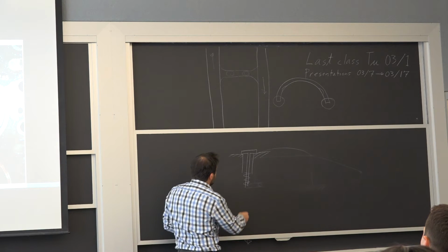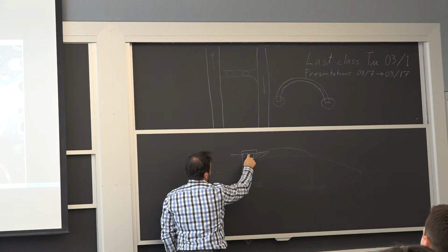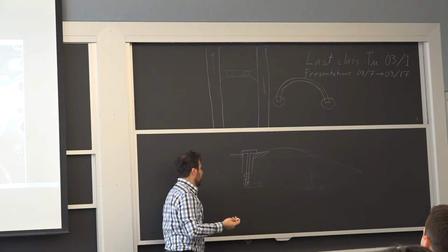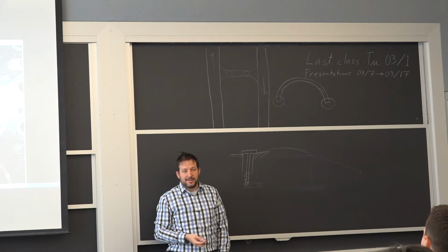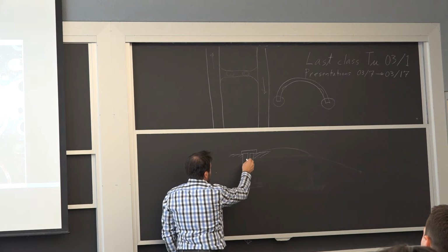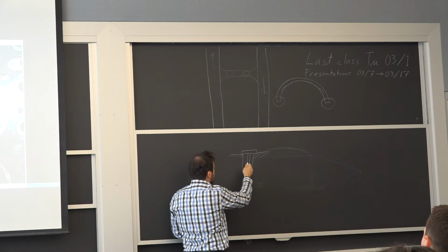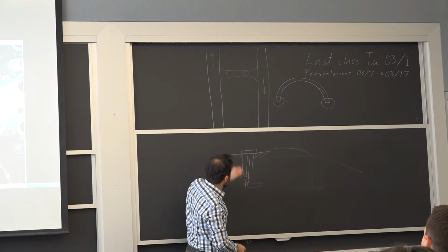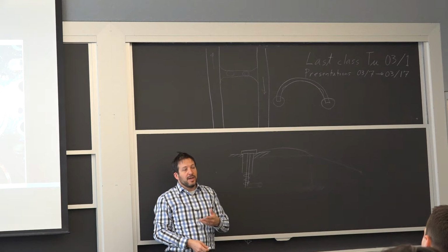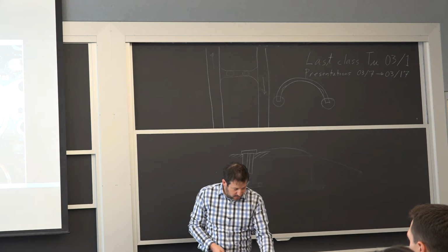There is very, very little force between the head of the valve, because it's only a spring, and the only thing you want to do is not have a whole lot of flow of gas when it's in closed position. So what happened is it failed right here at the junction, which means when it was coming down to close and you had the combustion pressure, there was a little too much force over time. And we are talking very, very large number of cycles. So they made these engines for a long period of time.